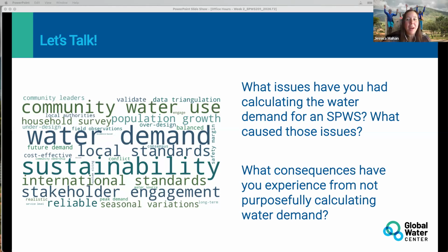Yeah, thank you. Okay, so it sounds like you're asking specifically about water storage or reservoir size. If I didn't catch that correctly, you can correct me. In my experience for solar powered water systems, our typical guideline is half the daily demand up to 3 times the daily demand as our range for how much water storage we would like to see. That can be a big range.